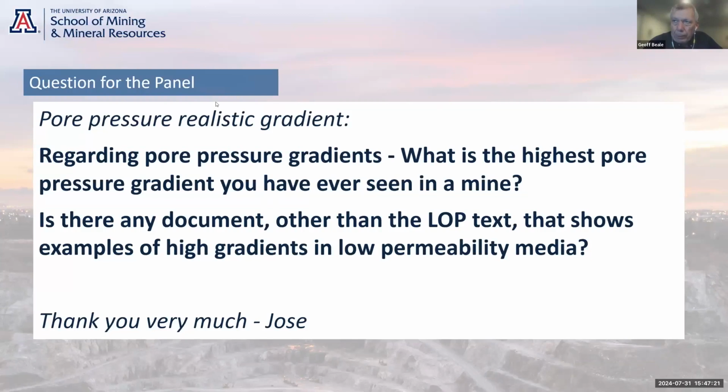The geological sequence was 2 meters of sand and then clay below that. So we had a piezometer in the sand. The sand was 2 meters thick. We had a piezometer at about 1.5 meters down in the sand, and we had the piezometer in the clay 4 meters down. As I say, the piezometer in the clay went from 2 meters to 65 meters.